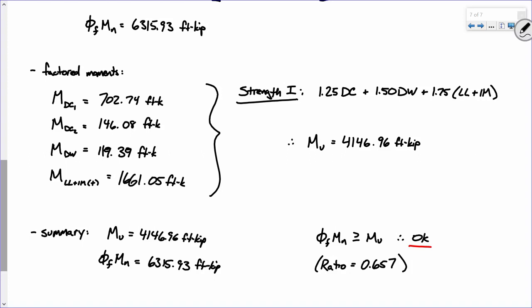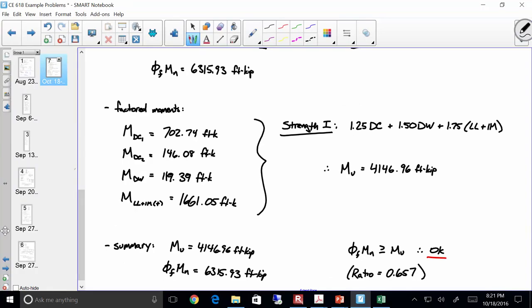We haven't looked at fatigue. We haven't looked at the constructability check. And I've mentioned this before, there are many cases where the worst loading condition that a bridge sees is while it's being constructed, okay? That's very possible, okay? We're not finished yet. But so far, the positive bending region's doing fine, okay? Sound good? All right. I actually think I'm going to call it tonight because what happens next is looking at the negative bending region.